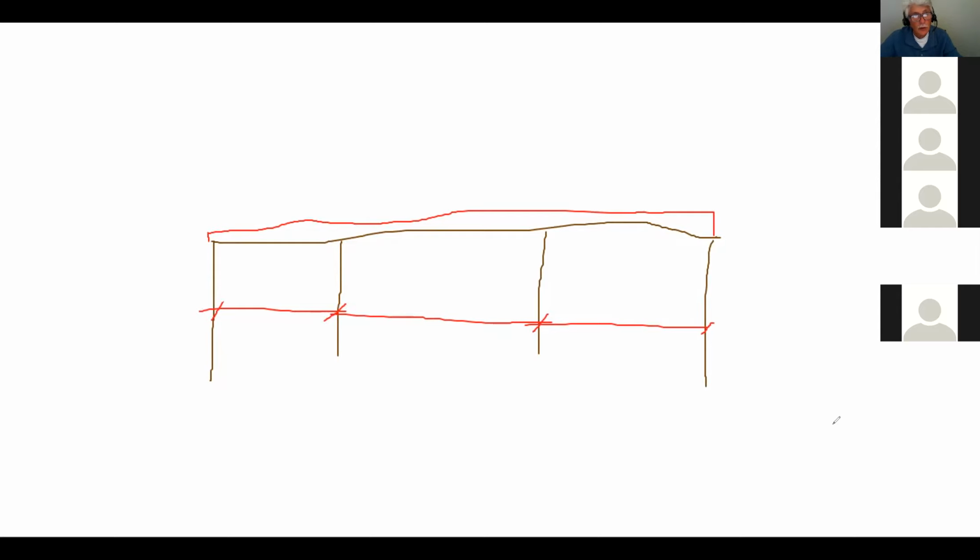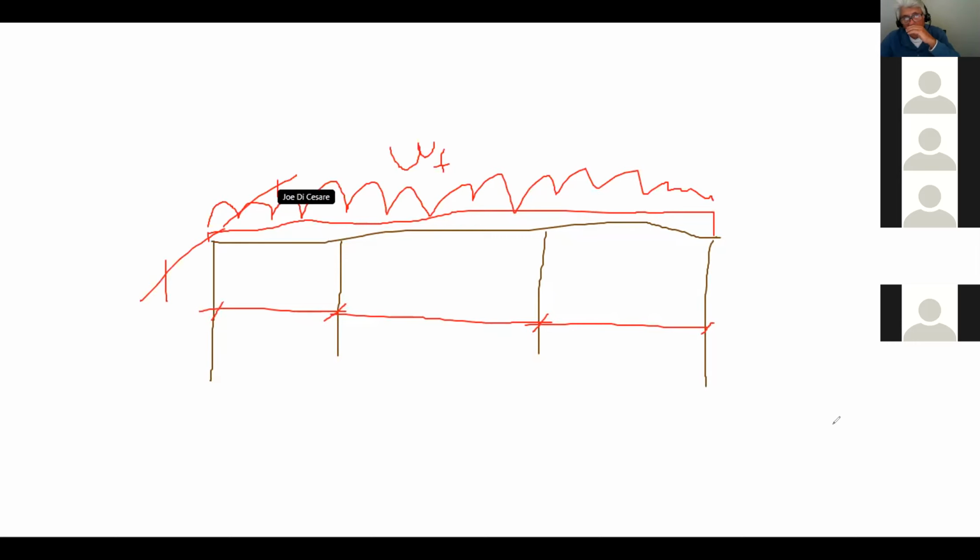So for example, if there are floor joists that are going this way, well, it's simple. You calculate the dead load of your floor, and then you know that it's 1.9 kPa for your live load, and so on and so on, and then this is the tributary width, so this is your WF. So that's number one.